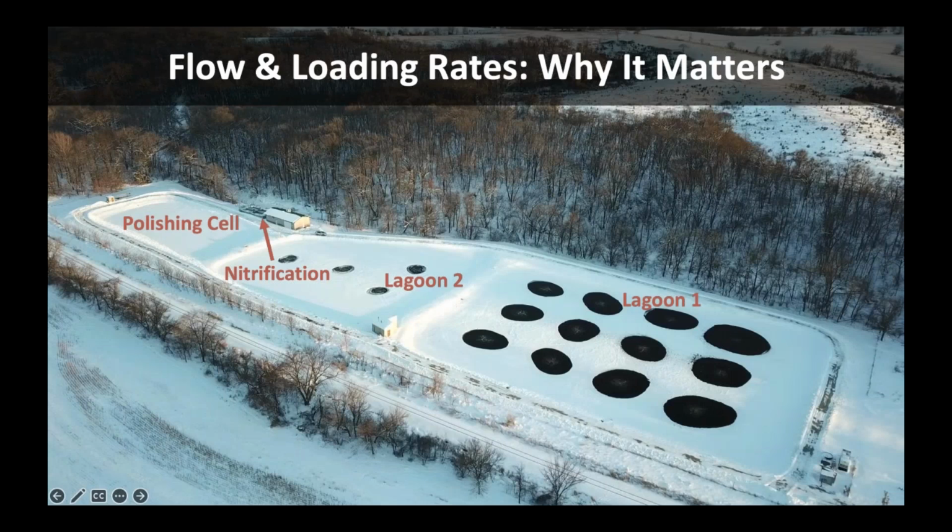So here's another reason why this is a big deal. It's not just that the treatment time gets reduced. It's also that if you have a downstream treatment process, and I'm going to talk about nitrification here, but it could be disinfection or some other downstream process. So this is a facility that we did. It's a 3-cell lagoon system, and they put our nitrification reactor near the back of the plant to help a lagoon meet an ammonia limit. Okay, so this is one of those Renaissance upgrades that we're doing a lot of work on now.